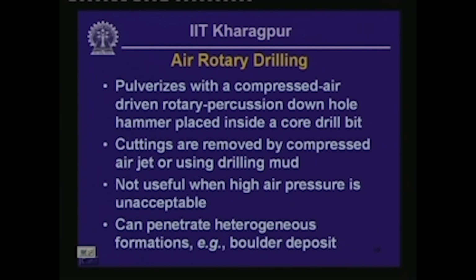This particular procedure cannot be used in situations where high air pressure becomes unacceptable, such as drilling through a water retaining dam or an embankment. This type of drilling process can penetrate to great depths. It could easily go to 1000 meter depth say, and it is very effective in penetrating heterogeneous deposits such as those composed of clays and boulders.